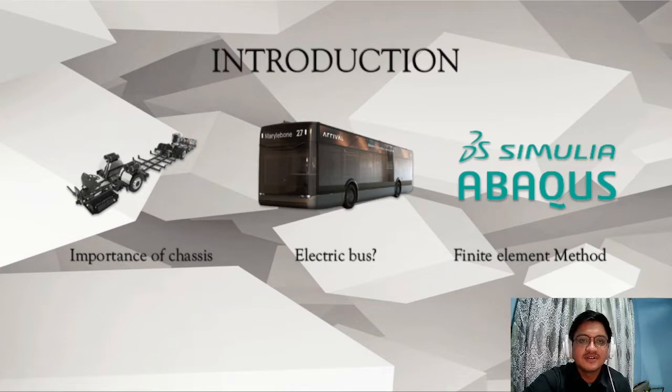By minimizing the physical experiment on the structure, the cost and time of experiment can be reduced, as well as boosting the productivity of the design process and development. The design of the structure is tested to pass the UN ECE Regulation Number 66, in which the structure must protect the residual space in the bus from collapsing before and after the crash test analysis.